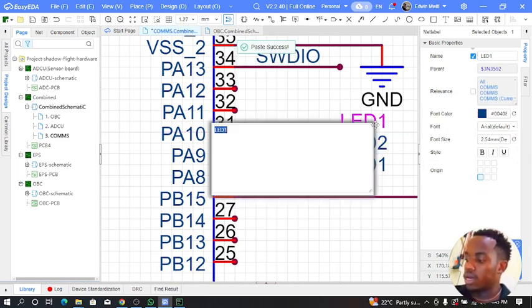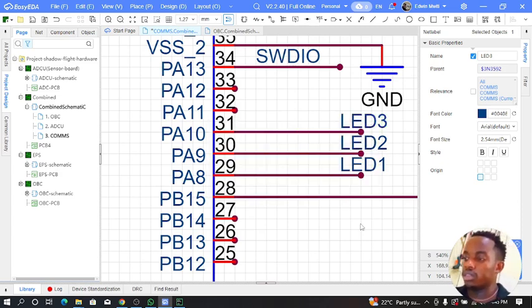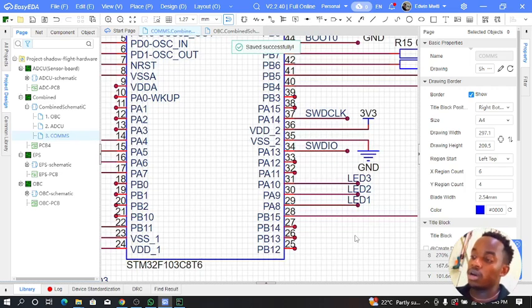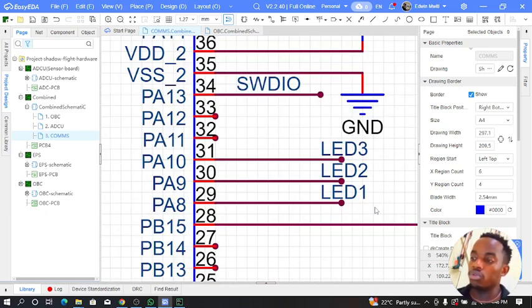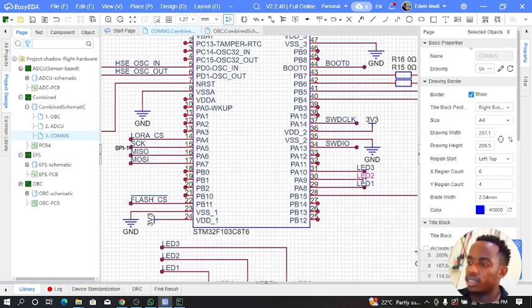And remember, these have no functional, of course, they have a functional use, but they are just for me to use to debug. It's always advised to have a spare LED or a spare button to test your inputs and outputs first. Plus, I can use them to show different states of operation. I can pulse them at different frequencies to show maybe a failure or success of some message transmission, etc. So that's why I'm adding these LEDs.